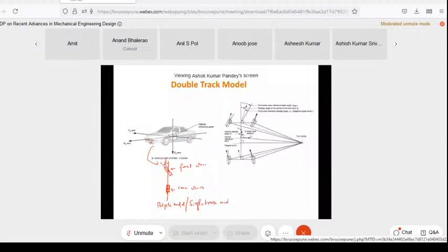Now let us say these two wheels are having different deltas, and all of them are steered. It means that you may have to go for all four wheels, and in that case we call it the double track model. So here you have all four wheels, and we try to find out the conditions. First of all, we have to get the forces which will act along the wheel and perpendicular to the wheel. So this is your longitudinal force, this is your lateral force, for all of them. Then you also need to find out the instantaneous velocity of each wheel.